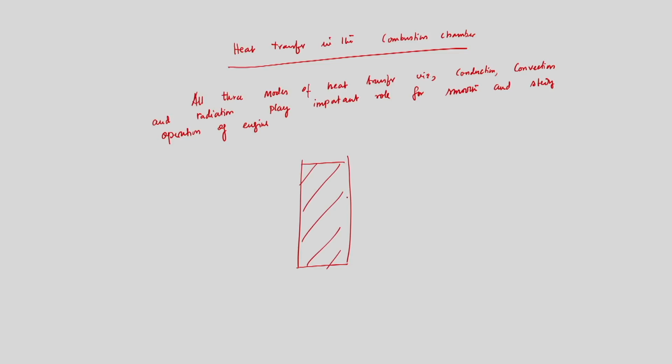Now, the temperature of the combustion product, or the gas, is very high, it may be 1000 degrees, then at the wall it is Tw and that is again much less. Then there is conduction in the wall, then finally we have loss to the surroundings and this is Tc. So, this is Hc, this is Hg, and this is delta x.